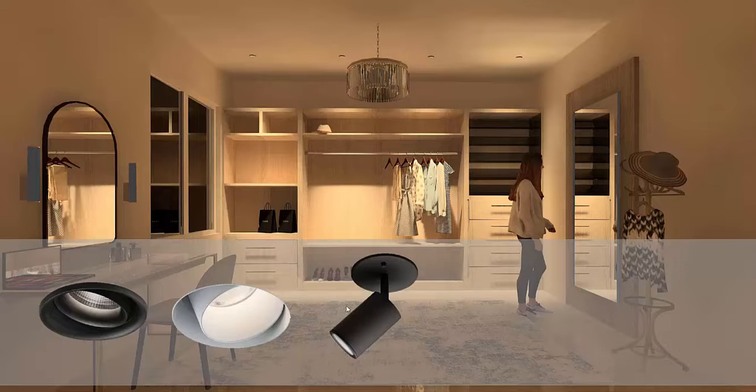But if you're using this kind of adjustable spotlights, you need to direct it only to the closet area. You can't direct it for a general illumination, because this will cause glare if you direct it for general illumination. But in case if you're using only to highlight the closet, then of course you can use this, but make sure you are placing at proper distance from this closet, somewhere between 1 feet to 2 feet away from the closet, and direct it towards the wardrobe.